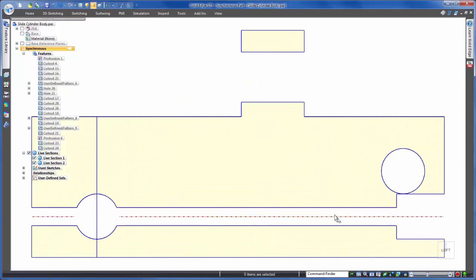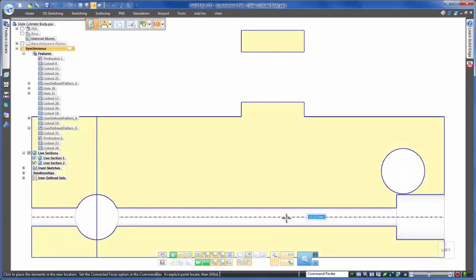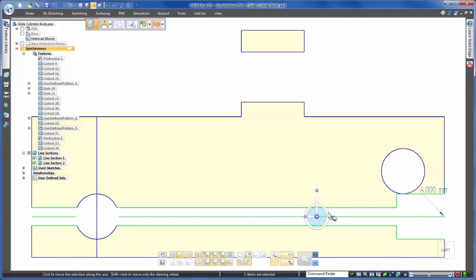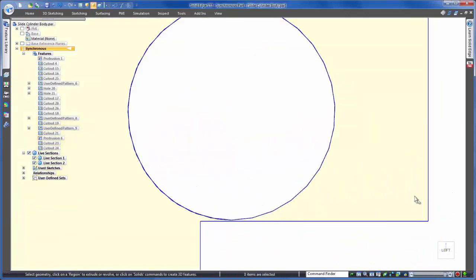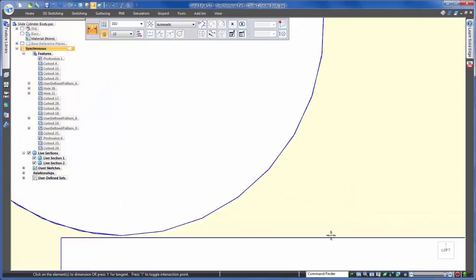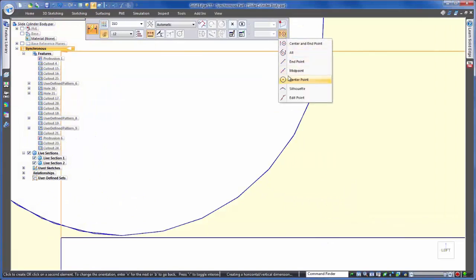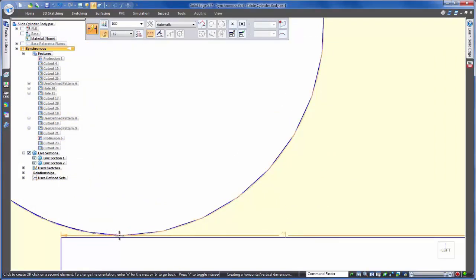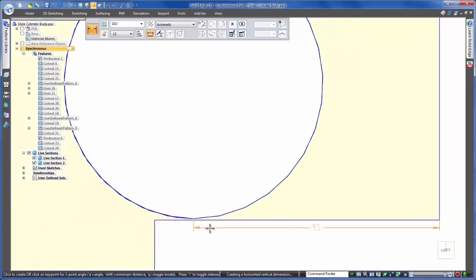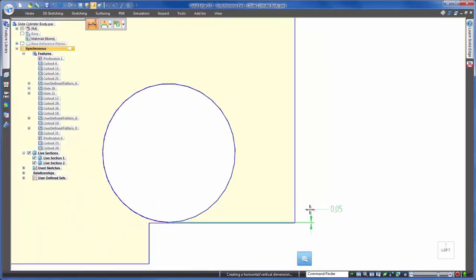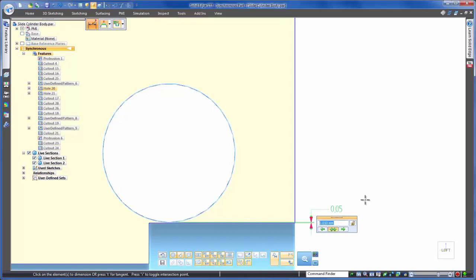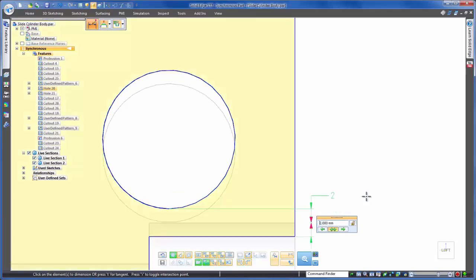We can simply drag this profile to see how the design intent is being taken care of, which of course is also modifying all of the solid geometry in the background, or we can use precision tools to make the edits. Again, we'll use the dimension tool to enter the precise value, choosing a symmetric input. Remember the multiple moves and multiple profile changes in the history-based approach? That's not the case here.